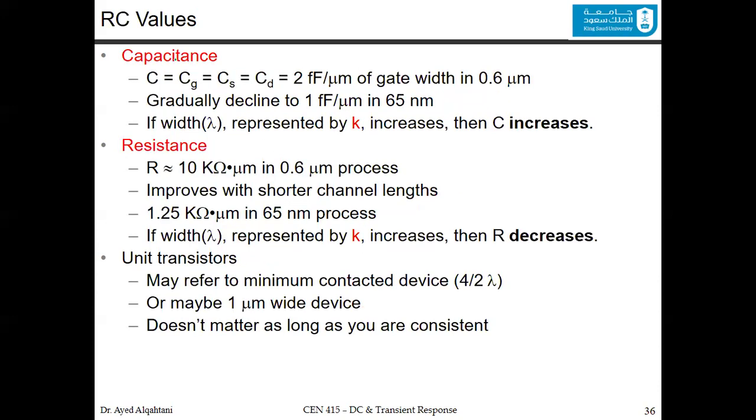So for the capacitance, we actually talked about this, and we said that we have the gate capacitance and the diffusion capacitance. The gate capacitance is equal to the diffusion capacitance at the source or the drain, which is given for a certain generation.